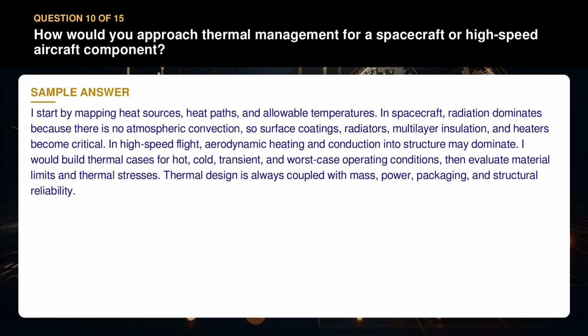I would build thermal cases for hot, cold, transient, and worst-case operating conditions. Then evaluate material limits and thermal stresses. Thermal design is always coupled with mass, power, packaging, and structural reliability.